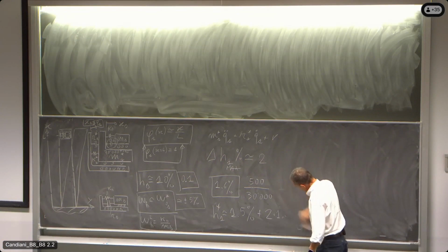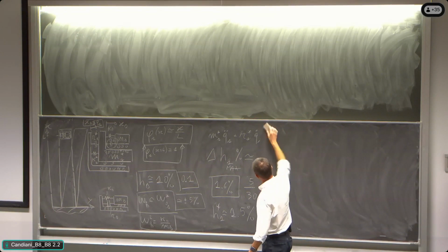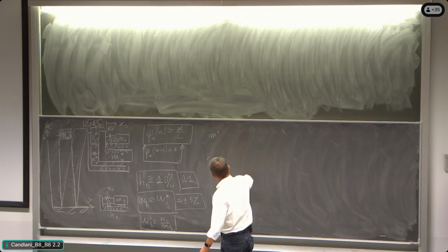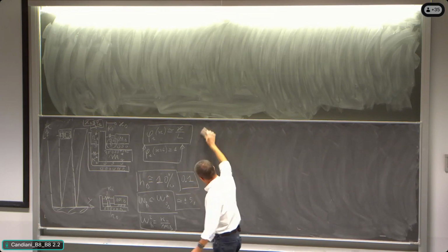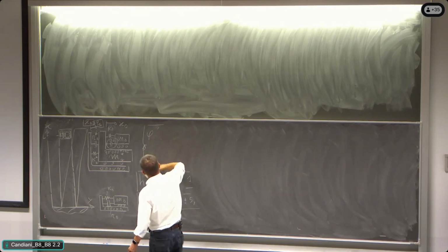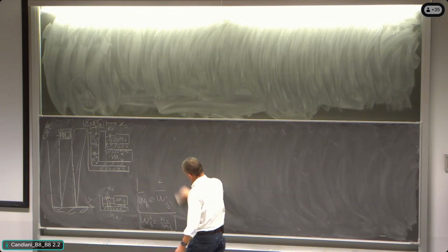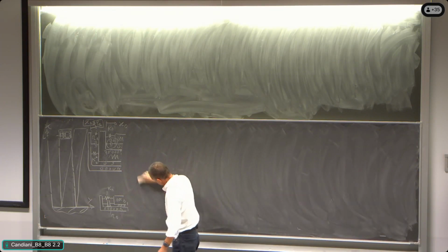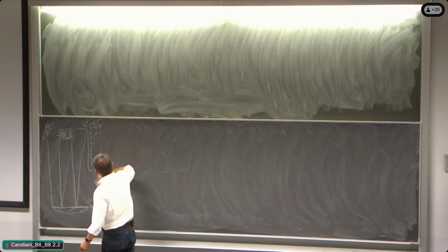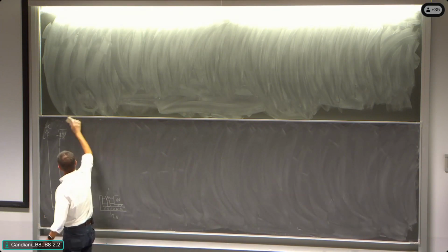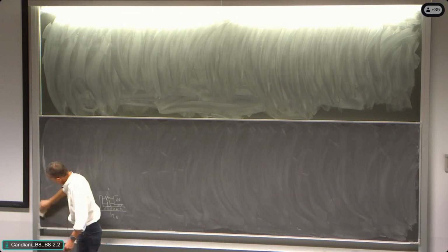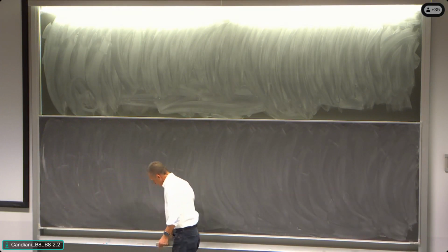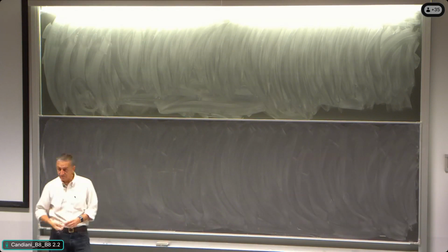The way in which it is made safe with respect to the excitation of the wind, vortex-induced vibration, as well as possible other behaviors, is through 4 active mass dampers that are protecting both torsional as well as lateral bending modes of the structure. It is an interesting example, and it was the first realization of a system like that.